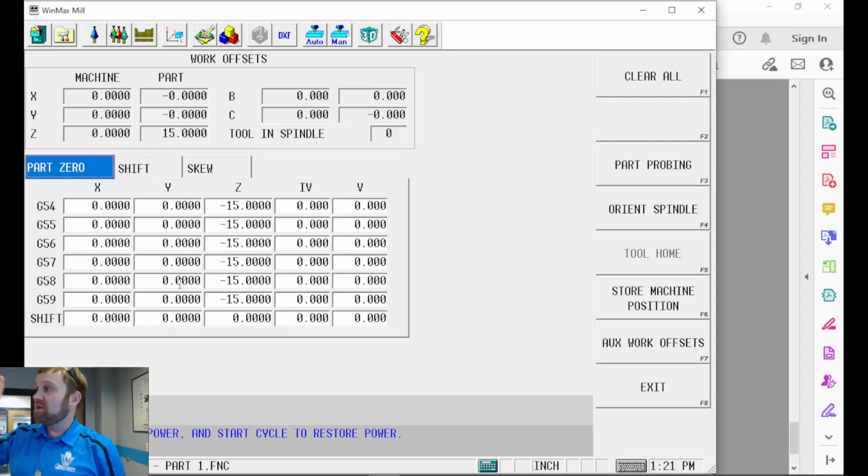If you know this, G54 is work offset 1. That's what you need to remember. And then when you get on a quiz and you see what's work offset number 3, what I fully expect to see you all do for the first few times, don't try to do it from memory, do this. 54, 55, 56. Okay, 56, G56. All right, just count them out.